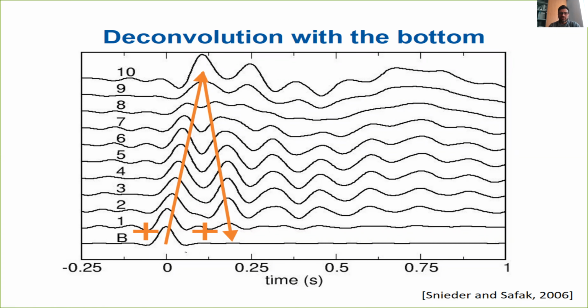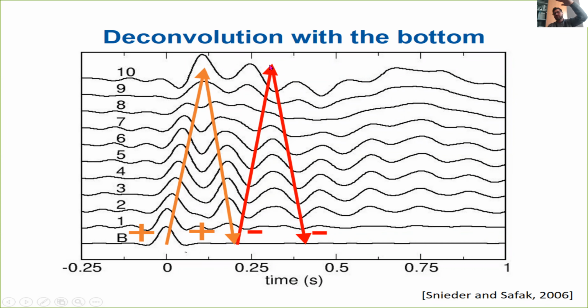Due to the contrast in the basement, the wave is changing the polarity and is propagating up to the roof again. It reaches the roof, and again, it's propagating down with the same polarity, which is a minus, and here it changes again and becomes a plus, and so on, until the effect of the damping, of the attenuation, is masking the propagation of the waves.